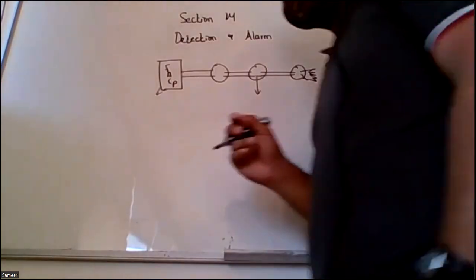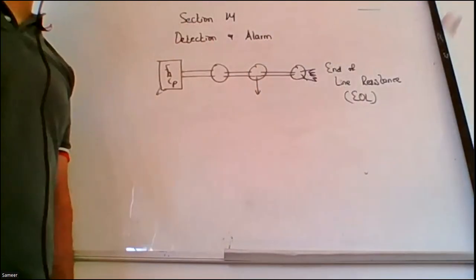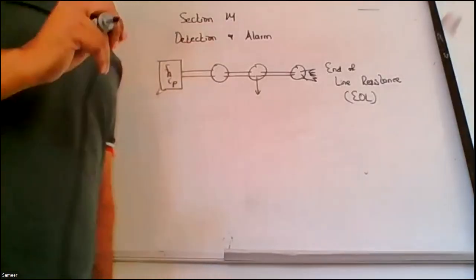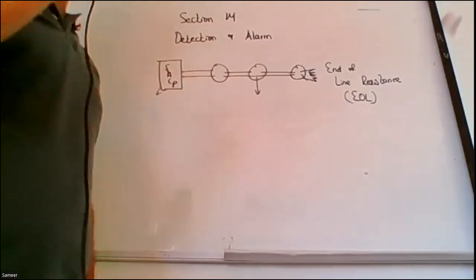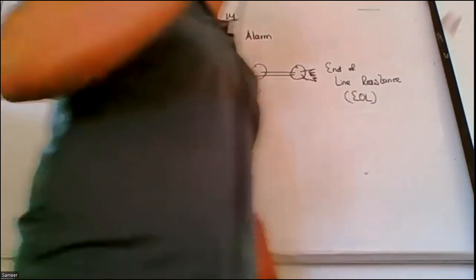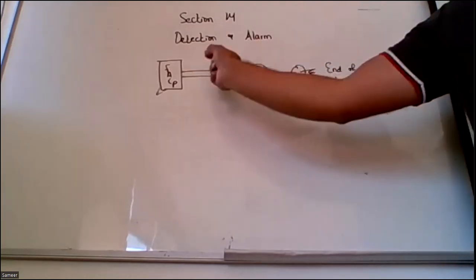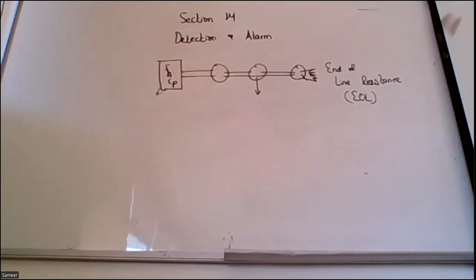This type of circuit, in which a device operates and initiates the whole circuit, is called an initiating device circuit. That's why smoke detectors, break glasses, sprinklers, zone control valves, and butterfly valves are all initiating device circuits, because once they operate, the whole circuit operates. It initiates the circuit and sends a signal directly to the fire alarm control panel.